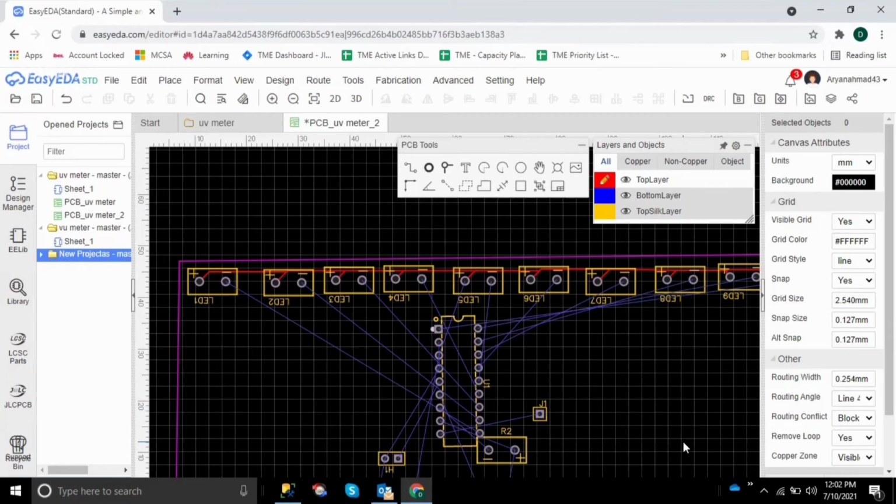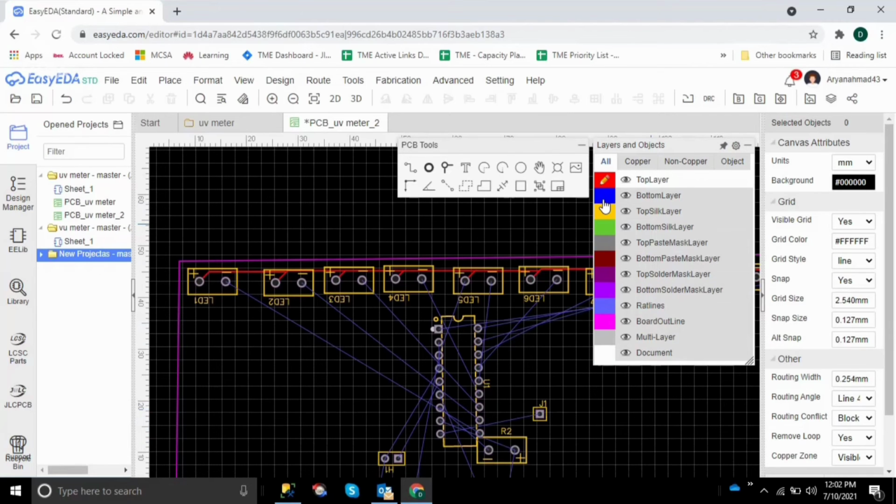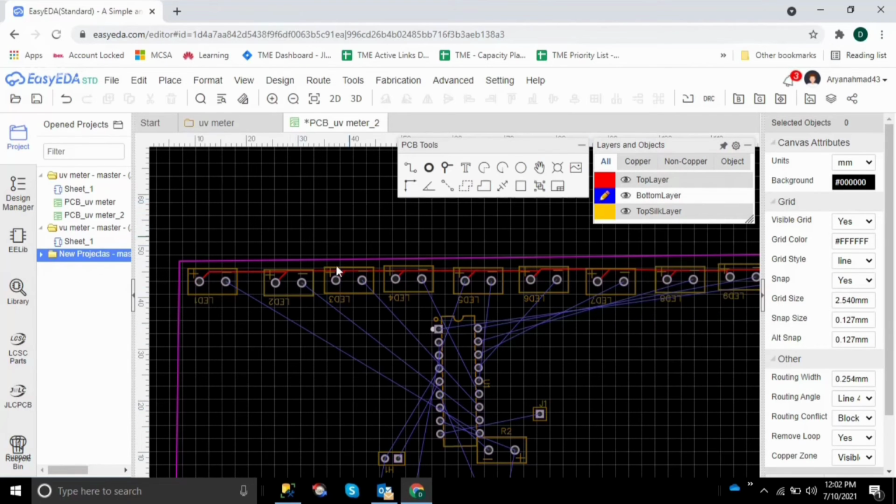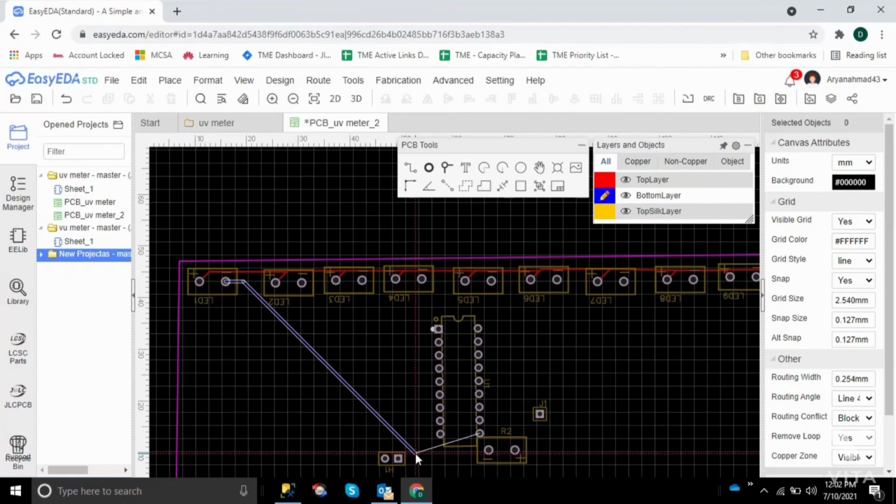Now what we can do with the blue one, and once the blue one is put, the ratsnest line disappears. Now we put the remaining ones to join them. So what I can do, click there, and then click automatically. It made a trace like that.